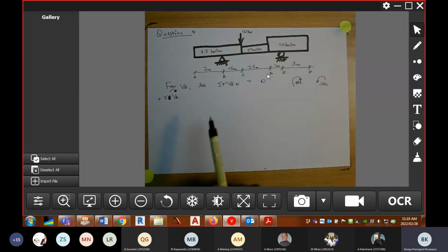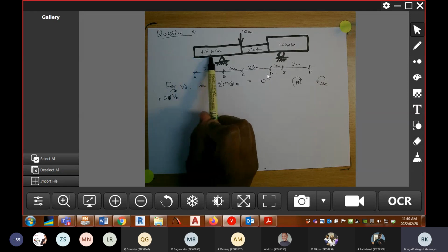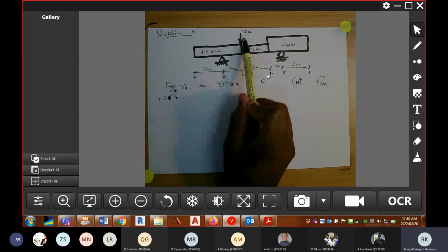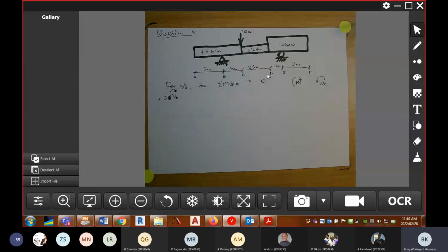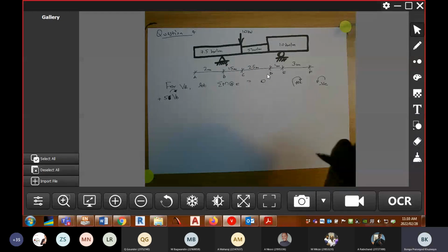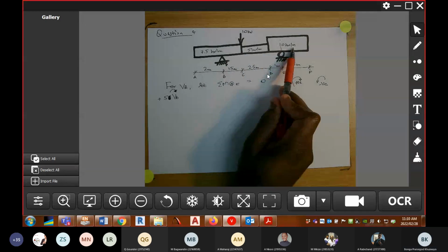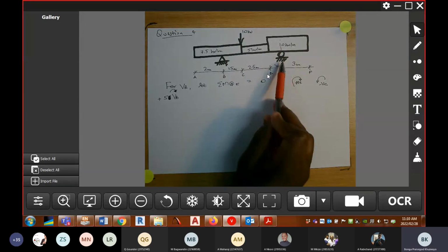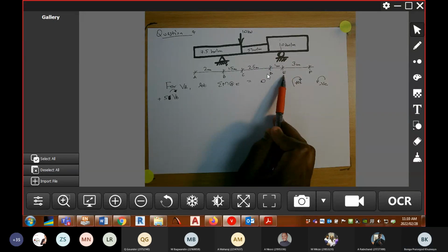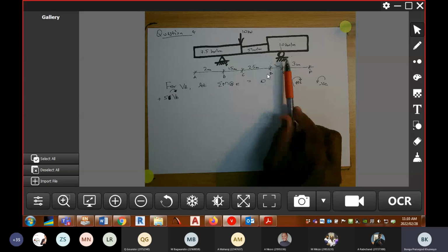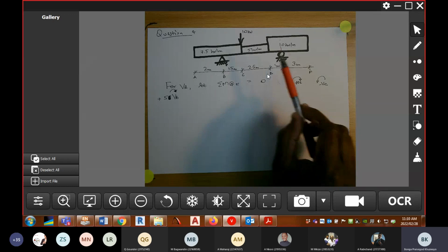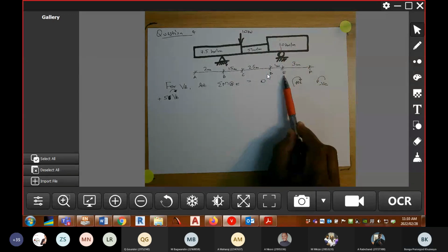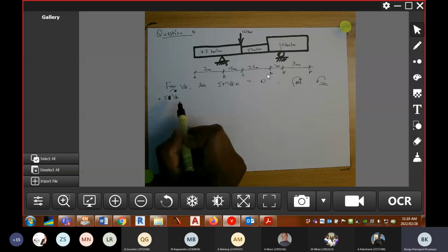Definitely not the 7,5 kilonewton per meter, not the 10, it can't be the 5 kilonewton per meter, and it cannot be the portion of the 10 kilonewton per meter UDL on the left-hand side of node E. We do have a UDL between node E and F that is causing clockwise rotation about node E. So I'm going to give it a plus.